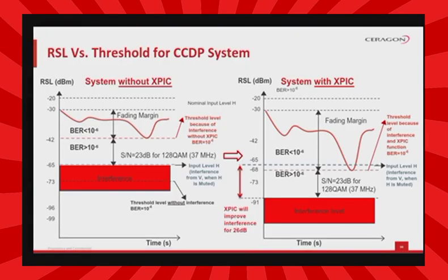In this next slide, we are taking the last diagram from the previous, showing the interfered signal from a cross-polarization interferer and comparing it to a system where the same interference is cancelled by the X-PIC mechanism. This is how our systems allow for double the capacity to be transmitted over the same channel. When activating the cross-polarization interference cancellation algorithm, you may see in the right side of the picture the improvement of 26 decibels, that practically drops the interference level of the interferer over the interfered to -91 decibels. Therefore, with the help of the X-PIC algorithm, we improve the performance of a system that uses co-channel dual polarization, allowing for double the capacity to be used by the network element.